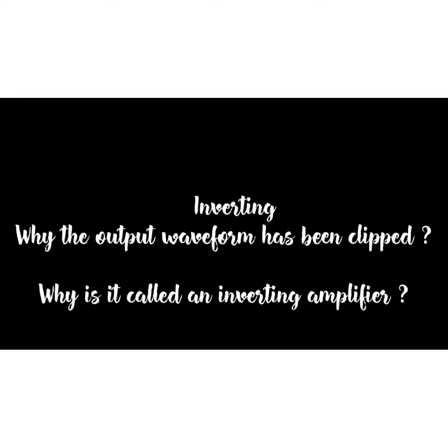For the first question, why has the output waveform been clipped? Output clipping can be caused by exceeding the input common voltage range or the input differential voltage range of the amplifier. Clipping can also occur when the output voltage range of the amplifier is exceeded.